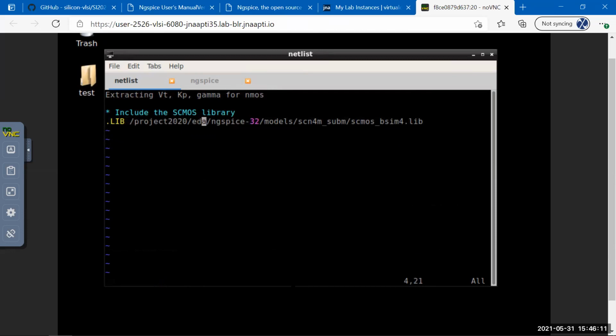So you do that, and usually I think NGSPICE doesn't require the quotes, but a lot of SPICE simulators do. So I'll put the quotes around the file name. Okay, and I think the nominal is called norm, so I'll do a norm. Now, there's a very powerful command in Vim to see what this file is.